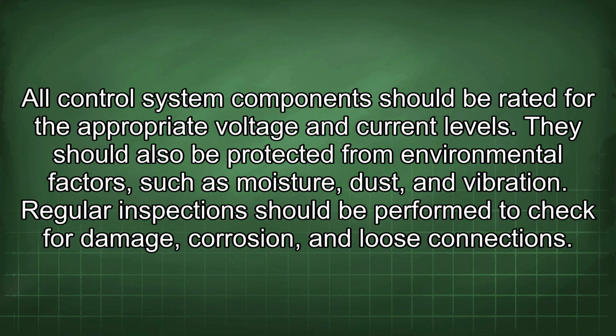All control system components should be rated for the appropriate voltage and current levels. They should also be protected from environmental factors such as moisture, dust, and vibration. Regular inspections should be performed to check for damage, corrosion, and loose connections.